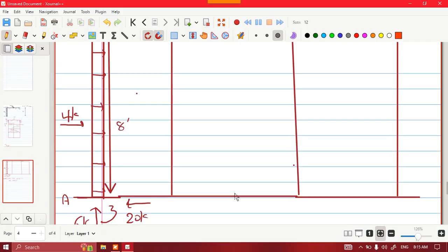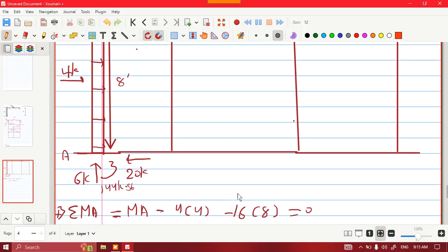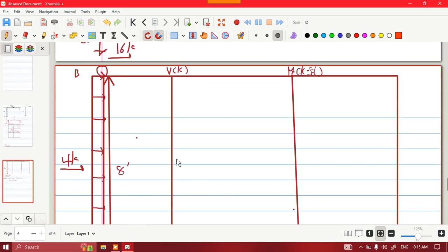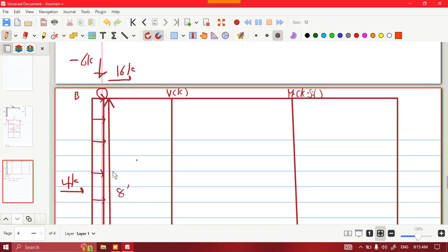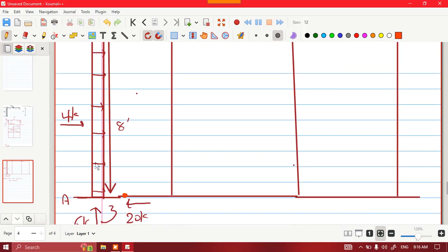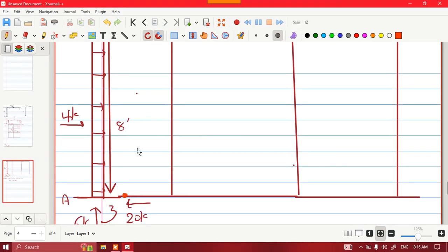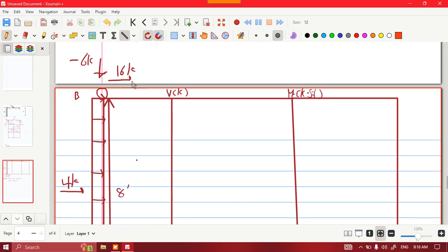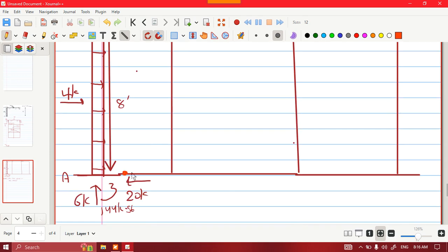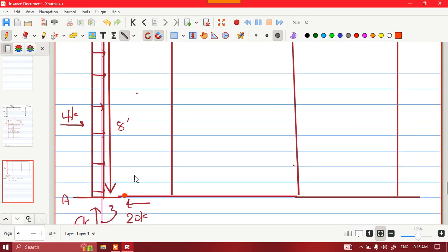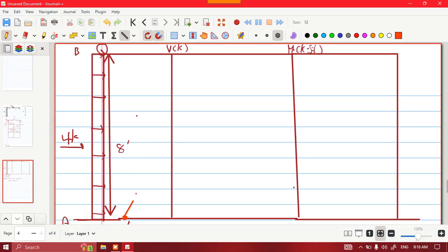I have plus 20 in this direction, and I'm going to decrease, for this distributed load, minus 4 kips per foot. So I'm going to decrease gradually until I reach plus 16 here, and then I go minus 16. We are going to decrease linearly, as you can see,